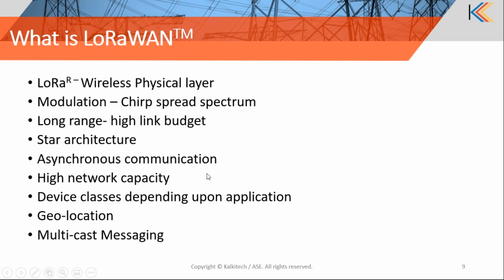It could be on event basis or periodically, but until and unless there is data to be transferred, there will not be any communication happening between the nodes and the base stations. That is also a huge advantage in terms of utilizing the bandwidth for other nodes and other data to be transferred over the network. And it has a high penetration rate compared to other wireless technologies.